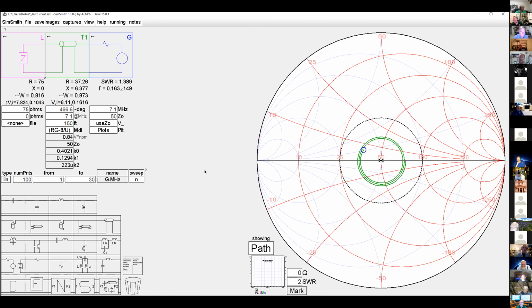And sometimes if you buy coax, you buy it from Roby's radio sales here, and I tell you, this is good 50 ohm stuff. It's not. It's really some special 100 ohm stuff that I got from a surplus sale somewhere, and you stick it in your system and it doesn't work right. And nothing's working right because it's not what I told you it was. It's not what you think it is. That's the other kind of thing that can happen.